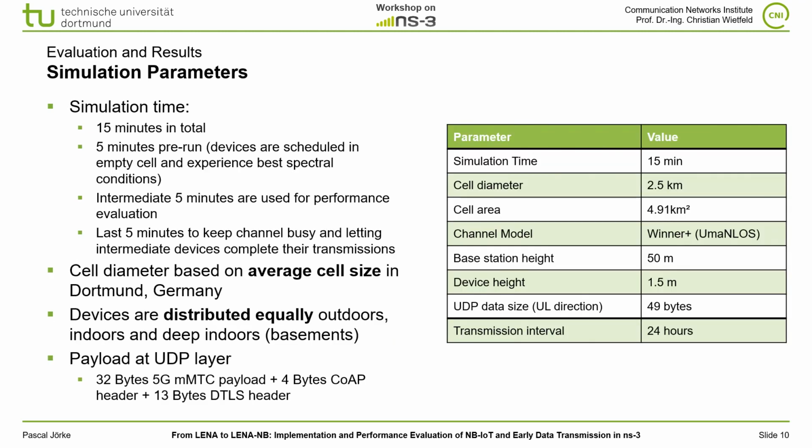But now let's talk about results. Using this framework, we have performed extensive simulation of different transmission modes and network densities. Each simulation ran for 15 minutes simulation time, including 5 minutes of pre-run, where devices are scheduled in empty cells and experience best, but unrealistic spectral conditions. The intermediate 5 minutes are used for this performance evaluation, while the last 5 minutes schedule new devices to keep the channel busy and letting the intermediate devices complete their transmissions.